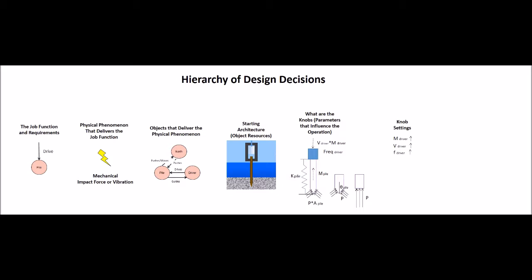Increasing the mass of the pile driver, the striking velocity of the pile, and the frequency of striking the pile would make it drive faster. Those three together constitute the energy that's going into the pile driver. If we increase this energy, we can drive faster. If we were renting the pile driver, then we could ask for a higher energy driver to drive faster. Going to a higher energy driver has its own problems and contradictions related to pile breakage and cost.